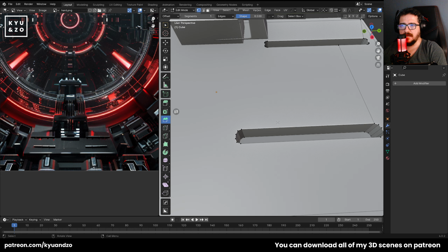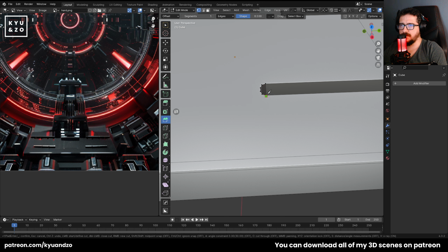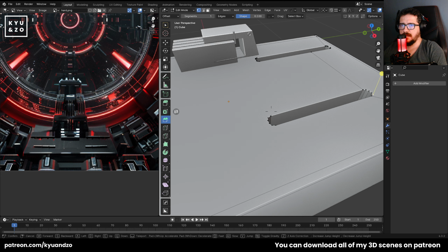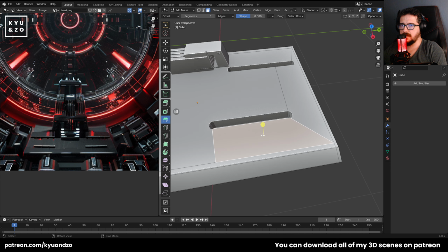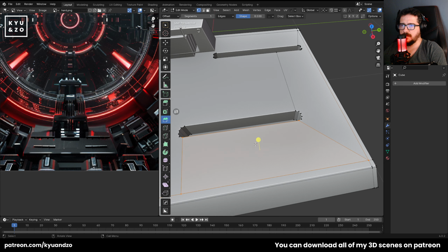I remember that I already explained it to you. So just the basic. Okay, turn everything here to quads. Let me explain it to you. Just like this. Is it quad? 1, 2, 3, 4. Yeah, look at this. It's loopable. You can check it. Check your surfaces if it's loopable.